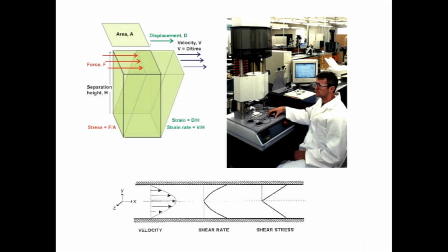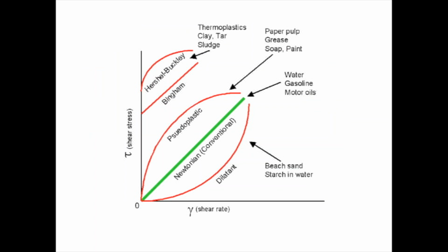So we're talking here about rheology, so I might as well introduce some basic terms. Rheology is, of course, a measure of flow behavior, or the force it takes to move per unit area. And this is looking at a property based on modulus or viscoelastic behavior under controlled shear rates or shear stress. So what might be familiar to you is looking at the stress versus strain, stress versus shear rate behavior of various fluids.